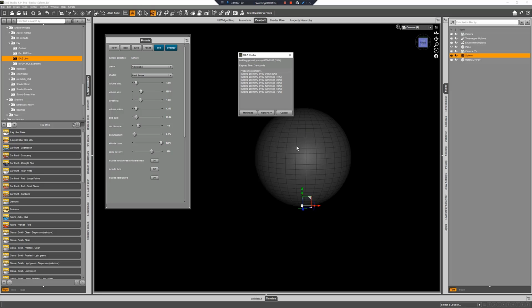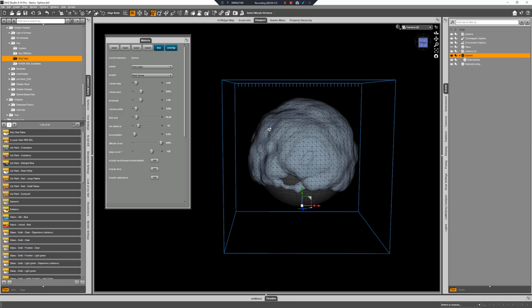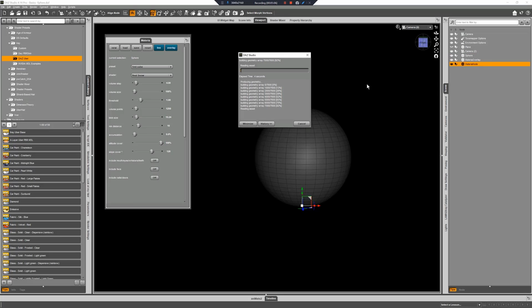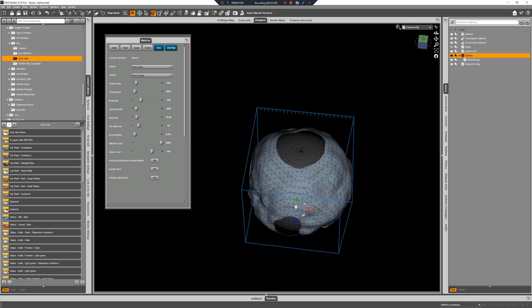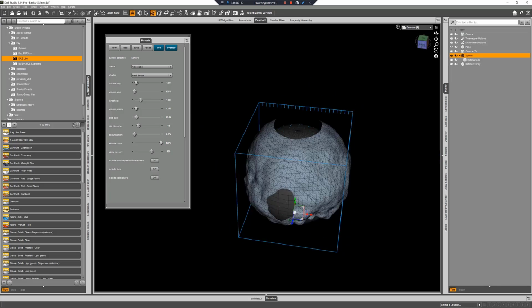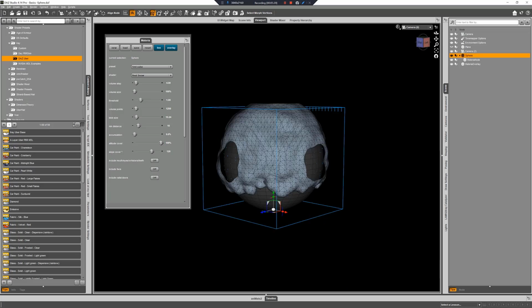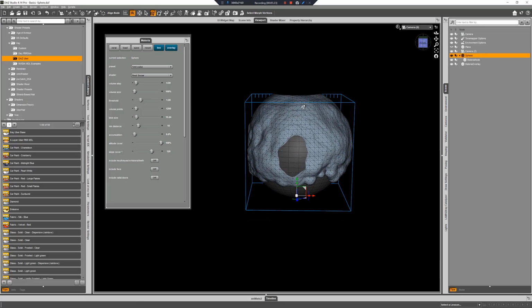Alright, the volume size basically establishes the boundaries of the simulation. So the generated surface cannot exceed these boundaries, and as you can see, these blue ones are basically the boundaries of our volume. It's not good advice to use a 100% volume size because that is very tight, and since the generated geometry will easily exceed the boundaries, you will end up with some part of the geometry not being generated. As you can see, they are being cut off, so everything that happens in Materia happens inside the volume.